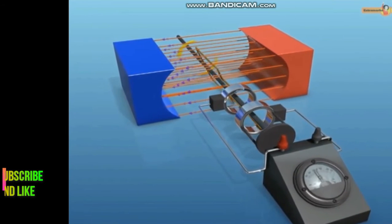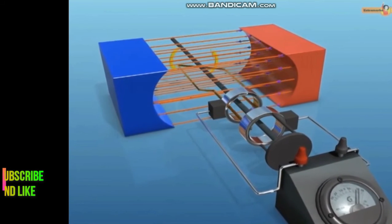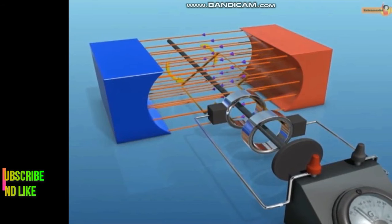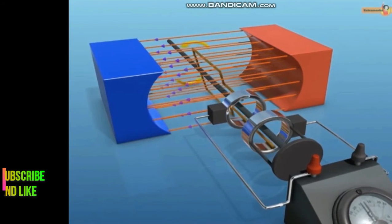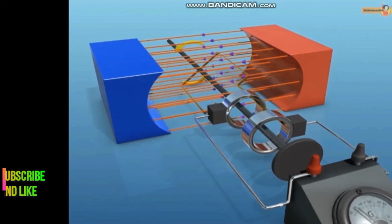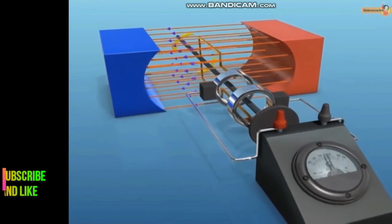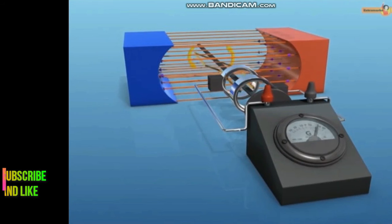As the two ends of armature are connected to an external circuit, an electric current starts flowing through it. This current is detected by the galvanometer connected in the external circuit. Due to change in relative position of the armature coil, the direction of current flowing in each arm of the armature coil keeps on changing, and hence the current so obtained is alternating current.